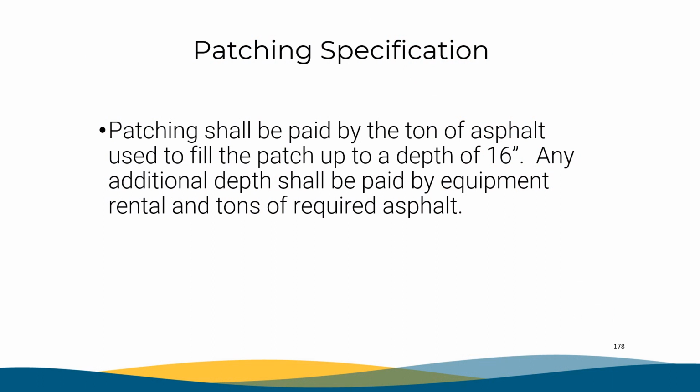Section 516 in the Standard Specifications book describes our most current patching specifications. This specification states that patching shall be paid by the ton of asphalt when filling a patch up to 16 inches deep. Any additional depth over the 16 inches shall be paid by equipment rental and the amount of tons required to complete the work.